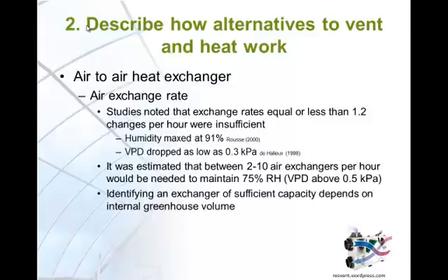Finding an exchanger with an appropriately high flow will depend on the greenhouse's internal volume. To achieve a high flow rate, it may be necessary to install several heat exchangers. Although these studies estimate a payback period between 3 and 9 years, payback will depend on outside conditions throughout the year and internal set points. Keep in mind that the studies here took place at latitudes between 45 degrees north and 47 degrees north.